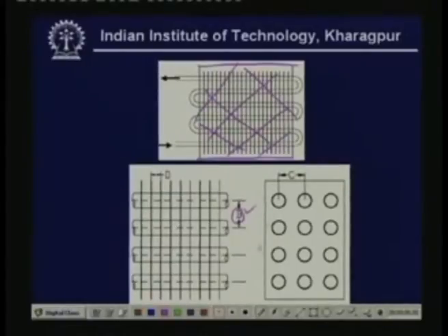C, this is the side view, is the center to center distance between two rows. D is the center to center distance between two consecutive fins, and T, as I said, is the thickness of the fin. So all these parameters are given to us. We have to ultimately find out the face area, and we also know the face velocity, which is mentioned as 2.5 meter per second.